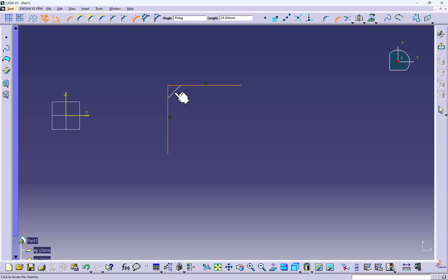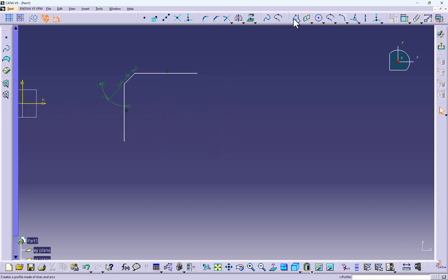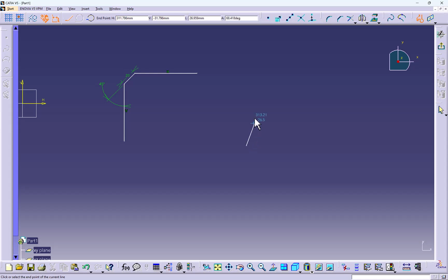You can decide the angle value. You can press the Tab key and that will be selected here. So 45, and what length we want to keep, we can specify, enter. So this is how it will be with hypotenuse, angle and distance. Now we have another way. If we want to add two different distances in the lines, we can do that also.